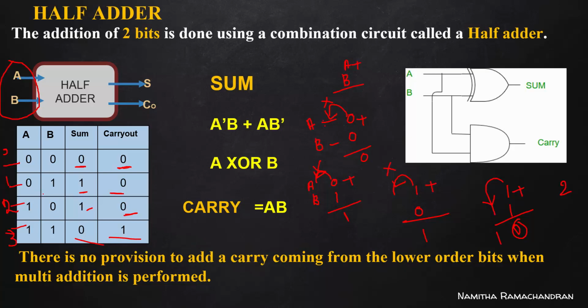Okay, so this is the case of our half adder addition. For this we need to generate the circuit for the sum portion and carry out portion. So consider this truth table and the sum part. Here it is, the sum part. And here, this 1 in the result sum part for the corresponding AB pattern 0, 1 is A bar B.